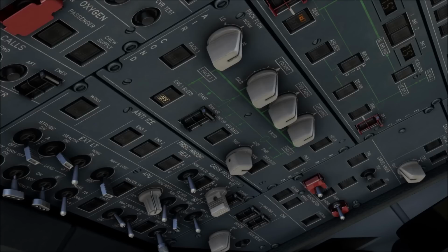When clear to start, area clear of obstacles, confirm. Ensure increased power jet blast does not constitute any hazard to people or installations behind the aircraft. Thrust lever on the supplying engine, adjust for bleed pressure.